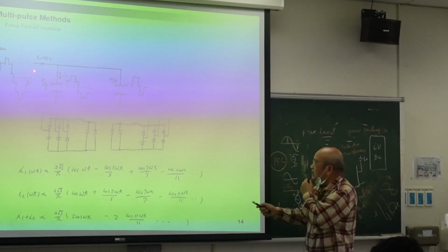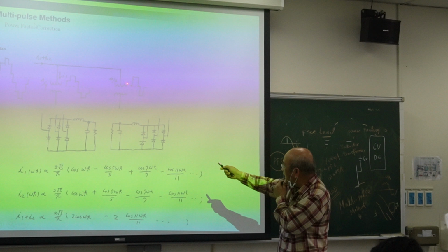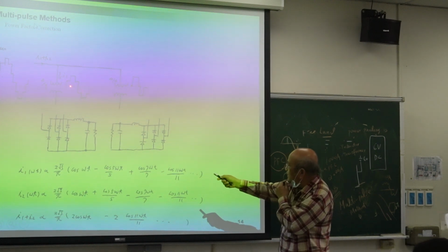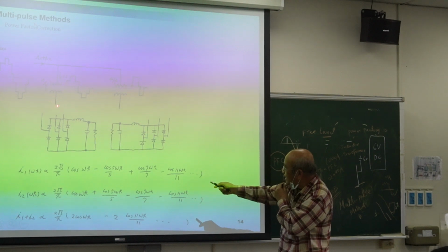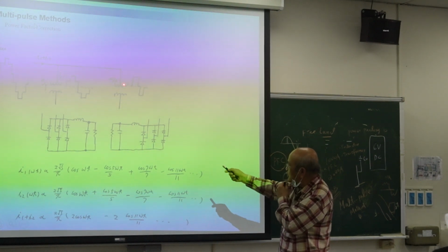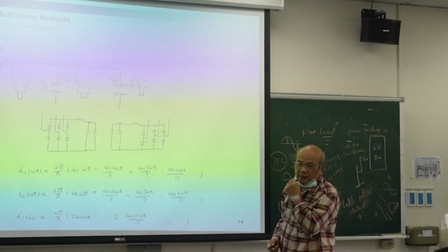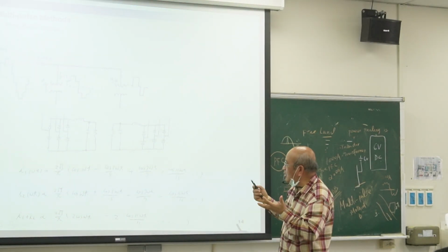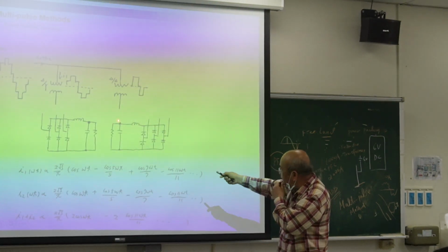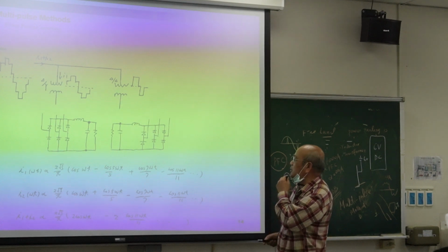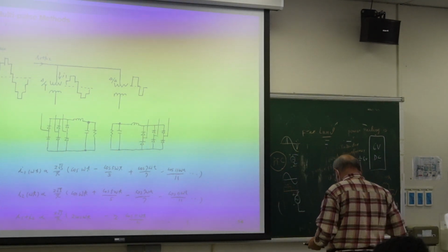They say, if I can use a transformer, this is delta, this is delta. I use another transformer, this is delta, this is Y. And I use two transformers in parallel to share the load. For example, you have 100 kilowatt, but here 50 kilowatt, here 50 kilowatt, total 100 kilowatt. Then it is okay, 50%, 50%.